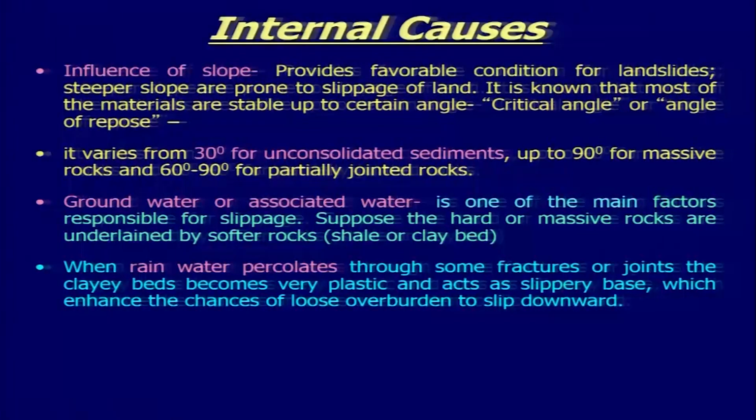So, when rain water percolates through some fractures, so again this is a geological structure. If you are having a massive rock, then whatever water is coming in will not percolate. But if you are having fractured rocks, then the chances of percolation of the water increase, and this will eventually reduce your shear strength.